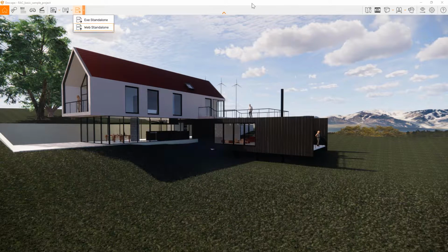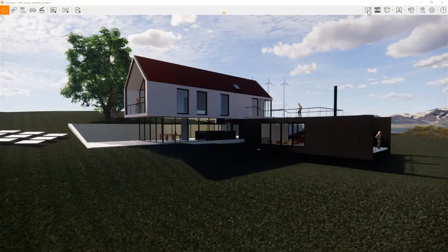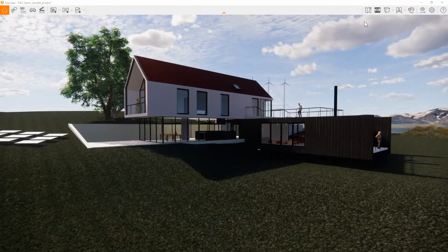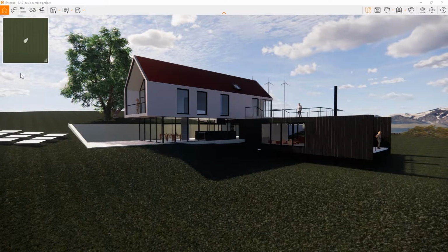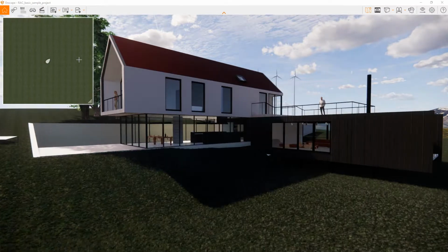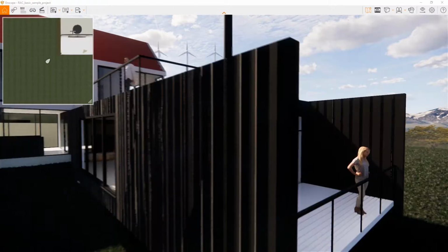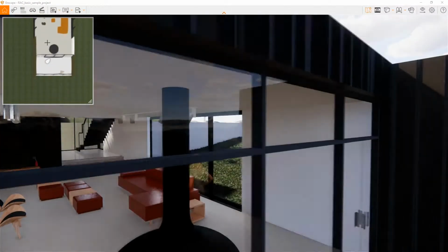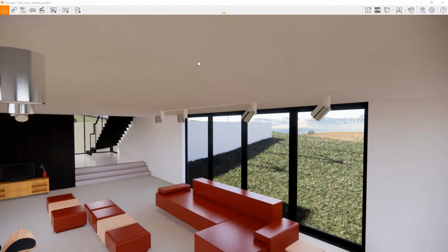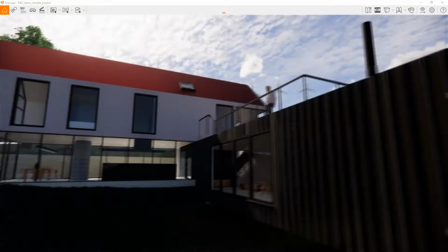So that's the left-hand side of the Enscape window. Now over here on the right-hand side, we have another way to navigate around. It's called our mini map feature, which again, it was just a simple window that was over here on the left-hand side. Now it's its own little tab up here. See, it popped up over here. If some user is not comfortable navigating around using the W, A, and D keys or arrow keys, they have this mini map feature to where I can click on any part of the model, and it'll take me over to that part of it. So again, I can close this. Let me back out here real quick to show you this next part.